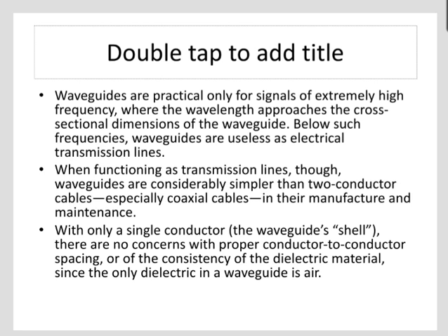Wave propagation through a waveguide may be classified into two, which we have seen, that is transverse electric or transverse magnetic, depending on which field, that is electric or magnetic, is perpendicular, that is transverse, to the direction of wave travel. Wave travel along a standard two conductor transmission line is of the transverse electric and magnetic mode, where both fields are oriented perpendicular to the direction of travel. The transverse electric and magnetic mode is only possible with two conductors and cannot exist in a waveguide.